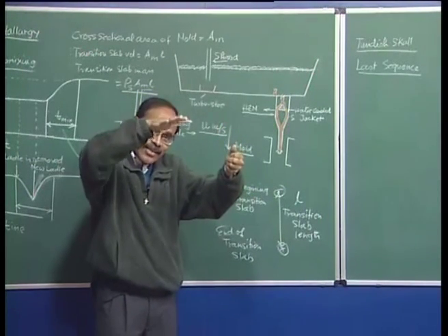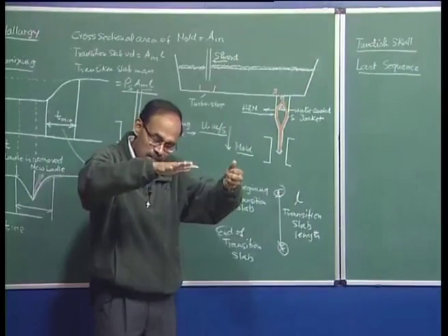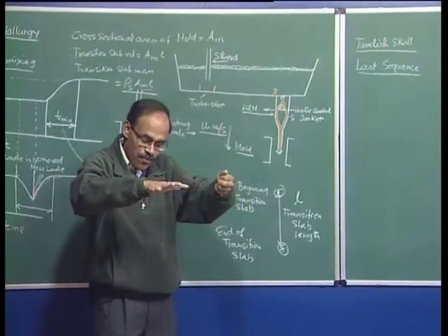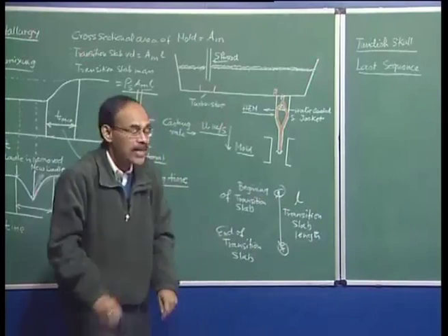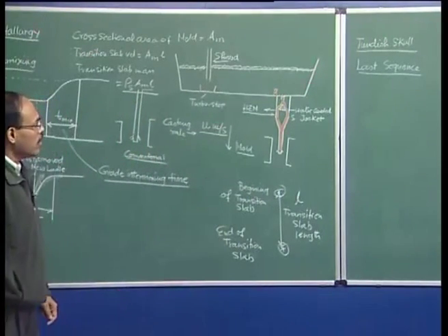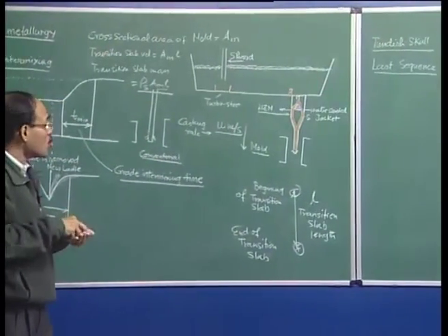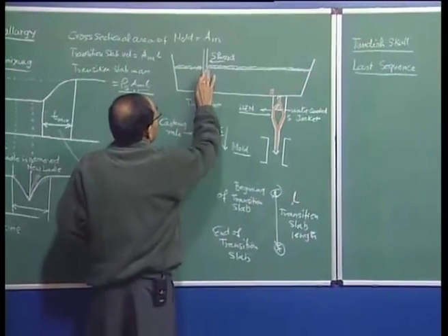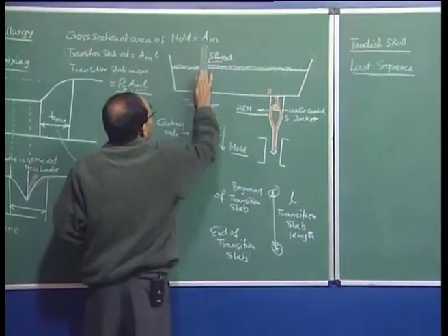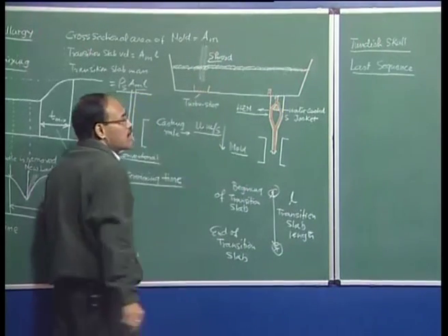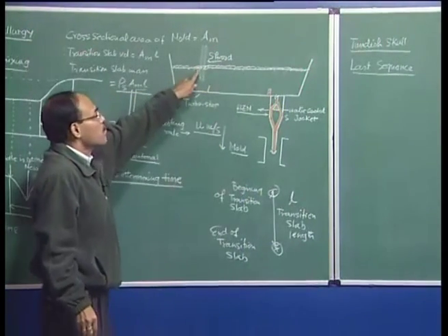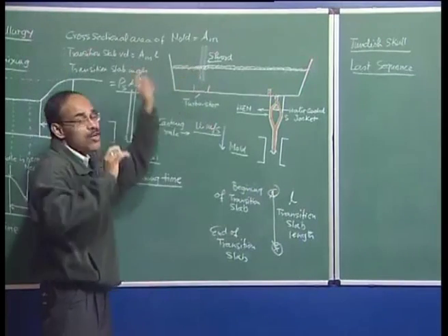So, the material in the ladle is going to be exhausted, and as it is exhausted, nothing comes into the tundish, and as a result the bath depth in the tundish goes down. So, at the moment this stops coming from the ladle, nothing comes in. This is the instant at which the material does not flow from the ladle.